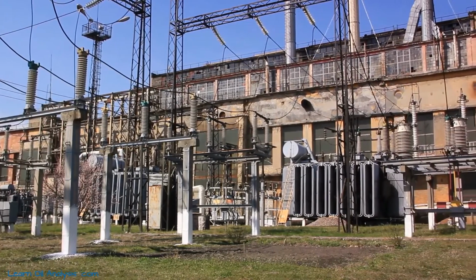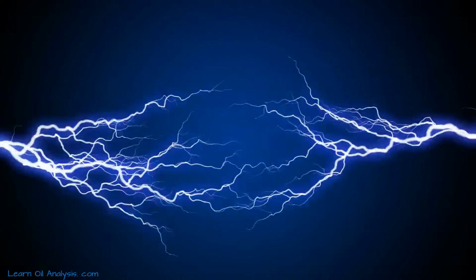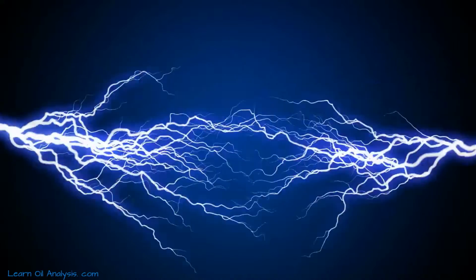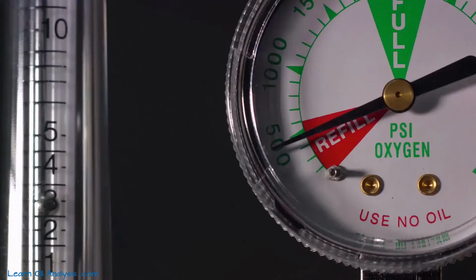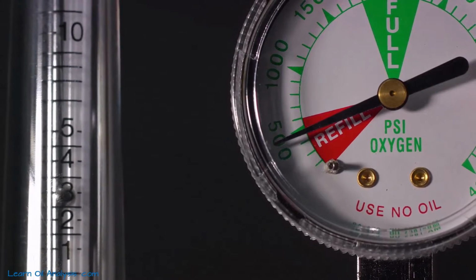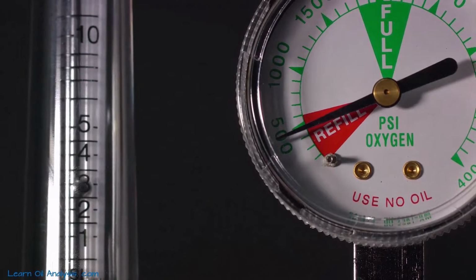The heat produced can be so intense that it breaks down both the insulating oil and paper, leading to the formation of specific gases that are indicative of this fault type. When a high-energy discharge occurs, you'll see a significant increase in the levels of hydrogen, acetylene, and perhaps carbon monoxide. You may also see a drop in oxygen. We will explain why later.